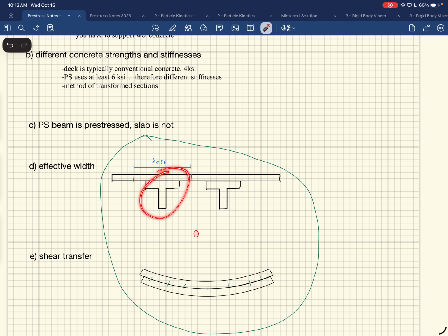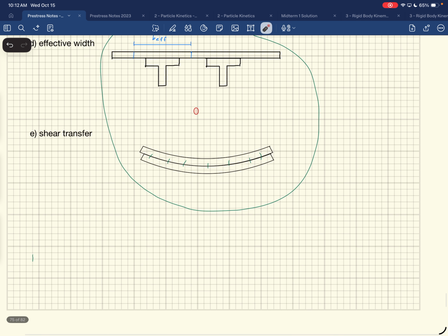Right, but it's very common, right? You have girders that are spaced out. Like the bridge we did in Wisdom, it was just a bunch of double T's stacked next to each other, so there was no need for a slab on top because the riding surface was just the top flange. But a lot of times you just have separate girders, and you have to tie it all together, and you put a slab on top of it. So how do we calculate that stuff?